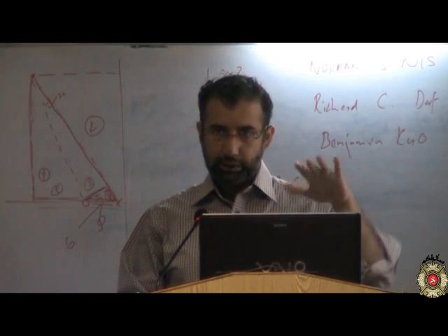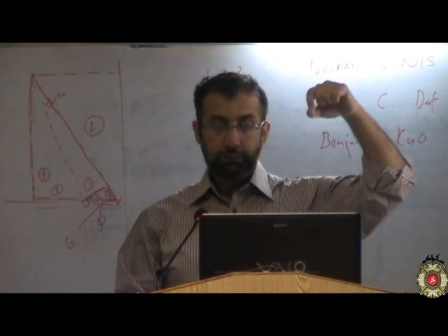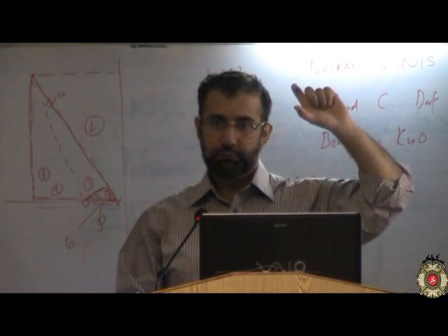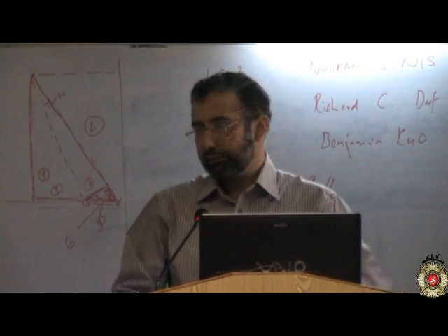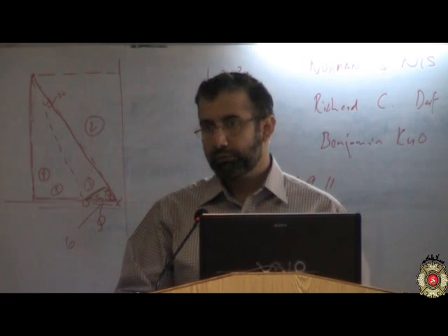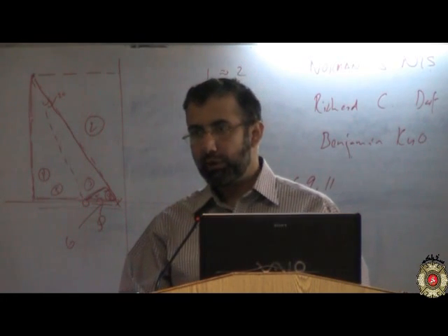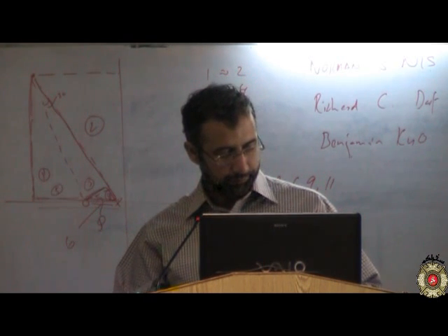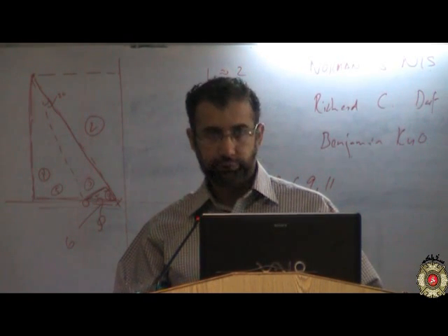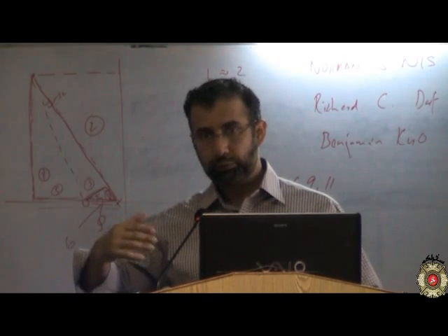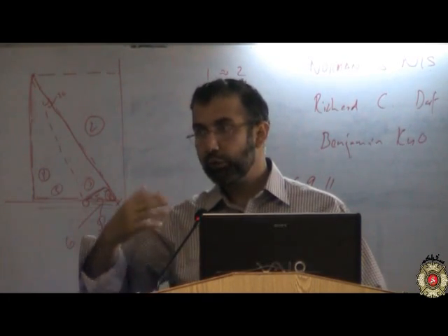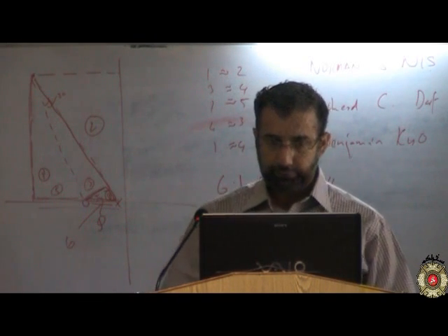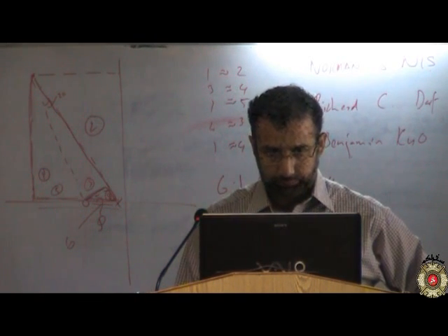Flow past a wing, low pressure on the top, high pressure at the bottom, there is a pressure differential that causes lift. The absolute value of pressure is not significant for us to know. We are generally interested in how much is the pressure difference. If it is less than atmospheric pressure or towards vacuum, the flow would flow inside. If it is more than that, it would flow towards the atmospheric outlet. So pressure differential is the important thing.